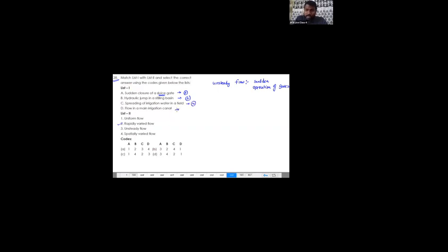And flow in main irrigation canal, that's going to be uniform flow. I have given all these examples. Where do you see uniform flow mostly? In irrigation canals. And whatever the spreading of irrigation water or runoff, that is spatially varied flow. If you suddenly close the gates or suddenly open the gates, that is unsteady flow. What is the answer? 3241. Option is going to be B. The only one question left over, 28 questions total.